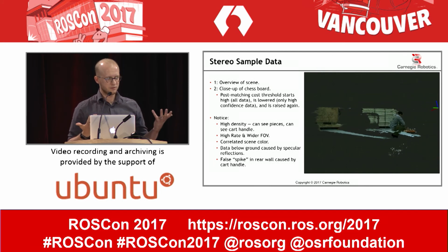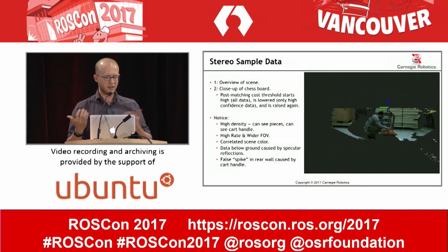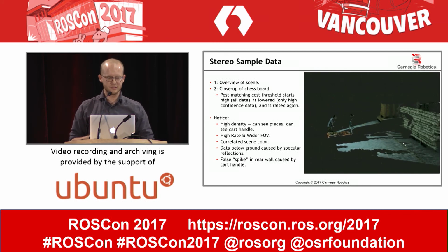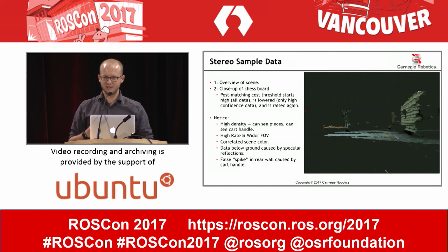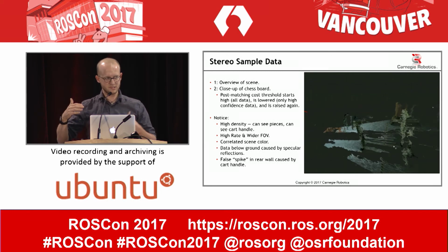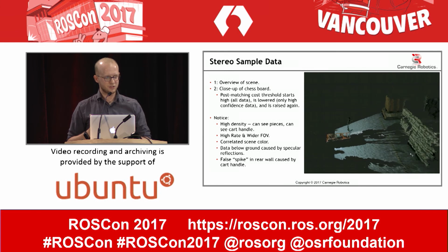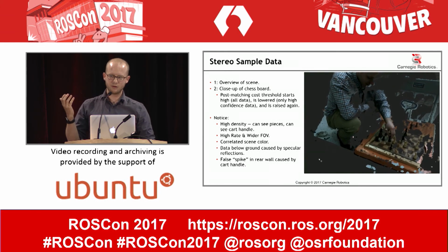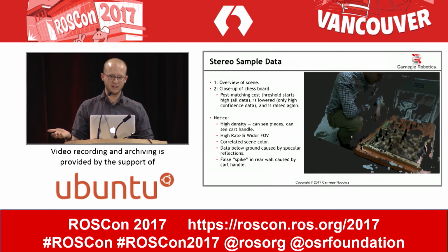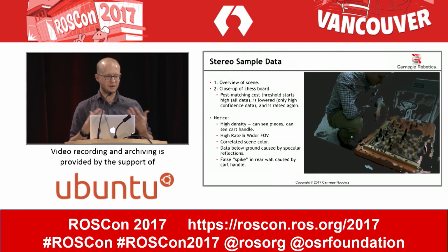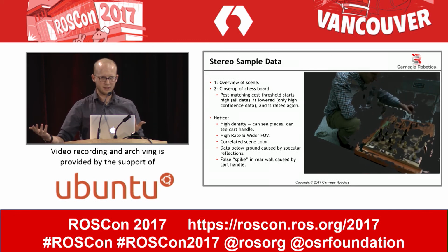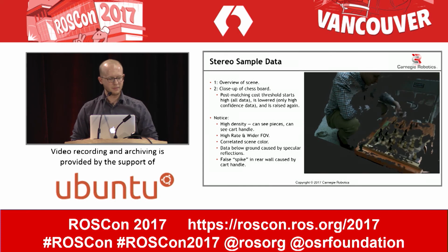Our cameras can be built with color imagers, so you have one-to-one perfectly correlated color with range, which is useful in some applications. But you also see a hole in this data in the floor and a bunch of returns below the floor surface. This is actually an invalid return. The camera is seeing a reflection of a light on the concrete floor, and it can't differentiate that reflection from reality, so it's actually giving us returns as though that light were reflected underneath the floor surface like a mirror.